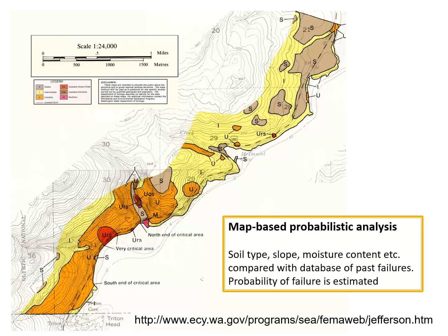In this case, you generate geospatial data describing the soil type, the soil strength parameters spatially, the moisture content, the slope of the ground, obviously. Sometimes vegetation is included. And then, using an algorithm, you could probably employ some kind of machine learning to help with this. I haven't seen that done, but I'm sure people have tried that.